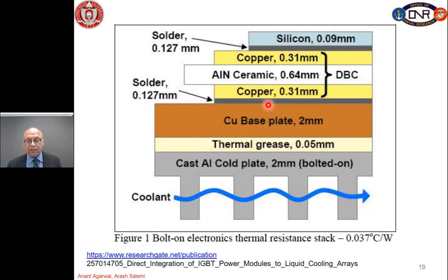On the top we have our silicon or silicon carbide power chip, which is soldered to what is called DBC, or direct bonded copper, which is essentially an insulating layer made out of aluminum ceramic with 2 copper films on both sides, and we can pattern the top copper film to connect various silicon devices in parallel, whereas the function of the ceramic is to provide insulation and isolation between different chips. For example, between the top switch and the bottom switch.